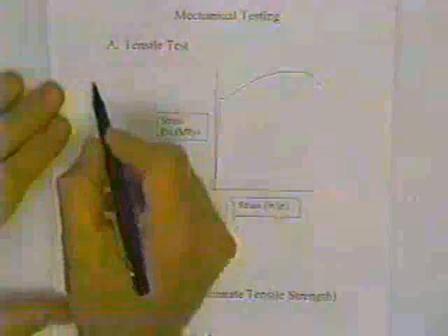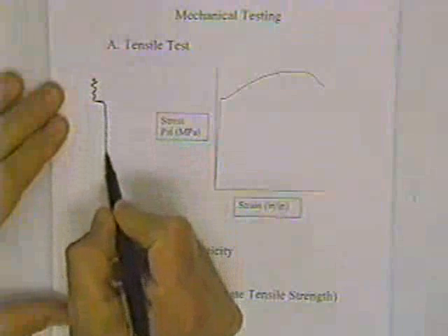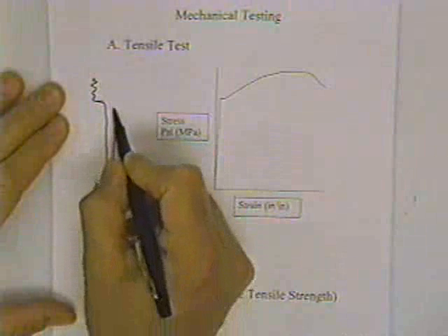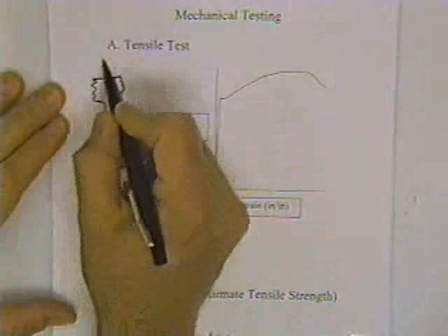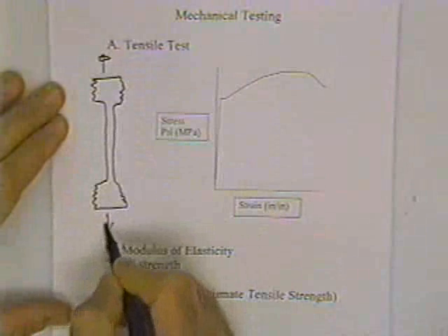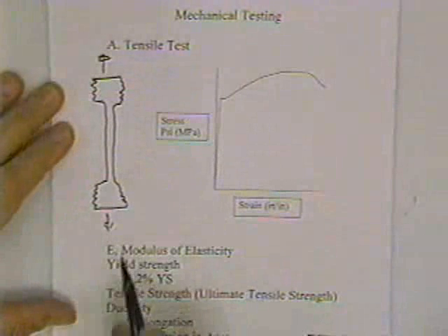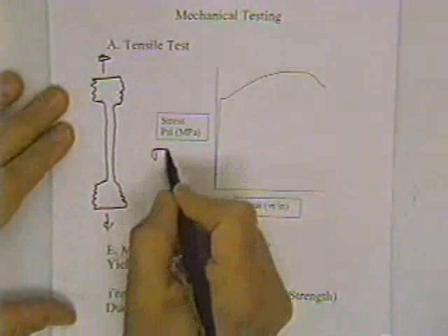Engineers will look at strength and ductility properties almost as a first cut for many types of designs. And in the tensile test, we have a uniaxial bar, we have a reduced cross-section, we put a force on, and we measure that force. We know the cross-sectional area, and we convert that to stress.